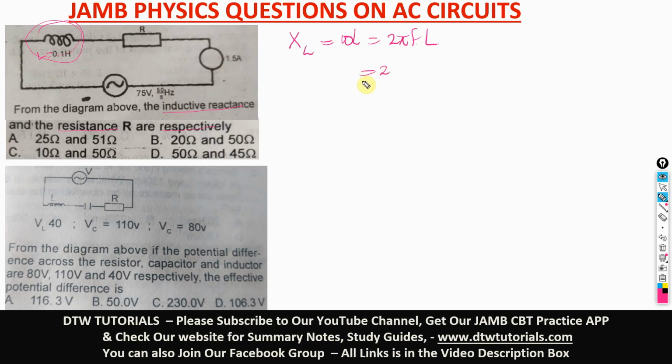So we have 2 times π times f, which is 50 over π. So that π would cancel out. 50 over π times 0.1. We have 2 times 50, which is 100, times 0.1, and you get 10. Inductive reactance, the unit is ohms. So our first answer is 10 ohms.